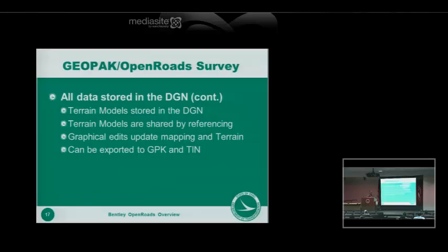When I gave the training to the ODOT surveyors, I had a user say, well, I'll open the survey file sometimes and go in and move the graphic, because maybe there was a manhole right next to a power pole and the symbols overlap. So I'll just go nudge that manhole over a little bit just so that it's clean, and they don't overlap.